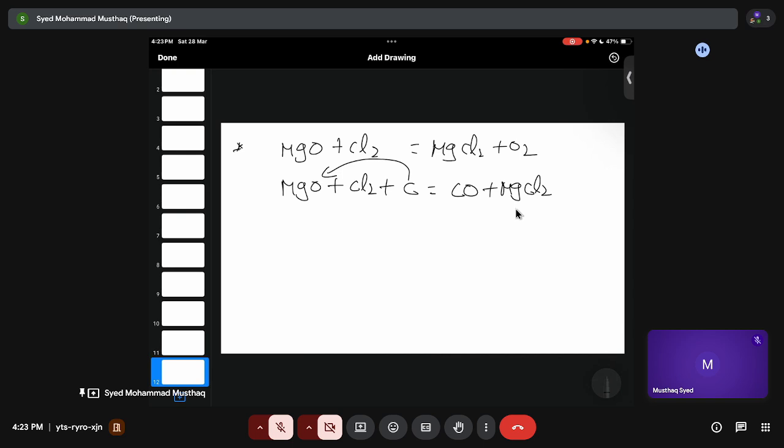If you take the natural one, it contains different impurities. Again, the same thing we are trying to do: add a reducing agent so that it will strip the oxygen, and the chlorine will react with your metal. So first we take coke and mix it with our rutile, and then we do briquetting or pelletization, depending upon the type of furnace you are trying to follow. Then we dry it, break it into the different sizes that we want, and then we do the fluidization